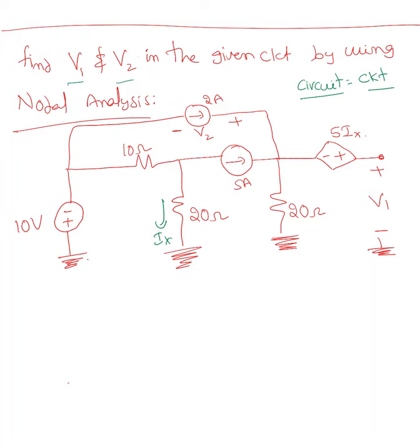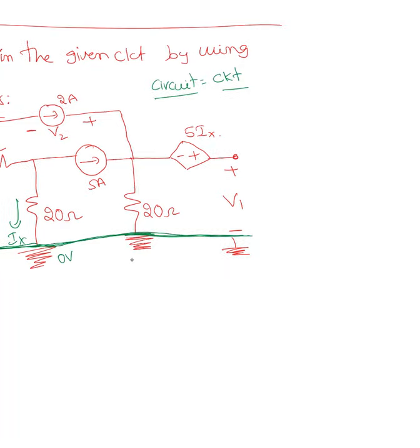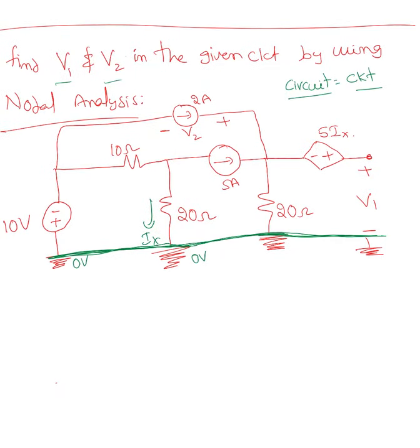This is grounded here. The voltage here is 0. The voltage here is 0. If both of them have the same voltage, we can kind of short circuit it. It's not going to work for every circuit, especially with operational amplifiers, which you're going to learn in the future. But here I can combine all of these. I mean, what I did, I connected every ground here.